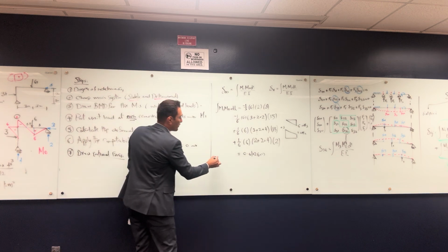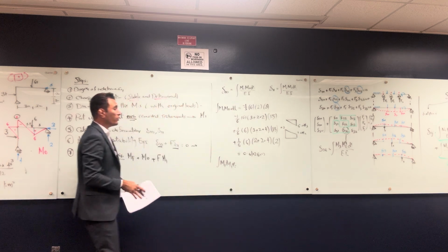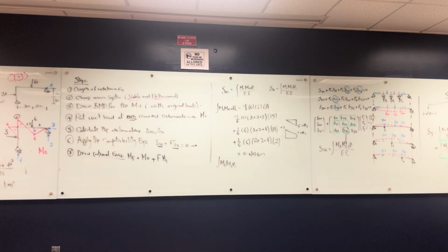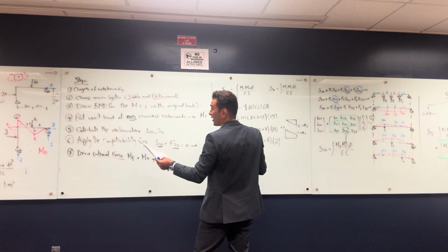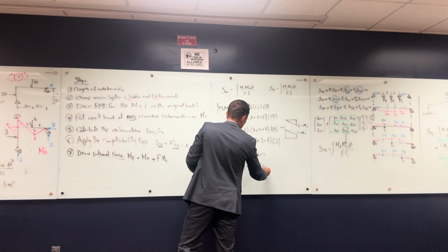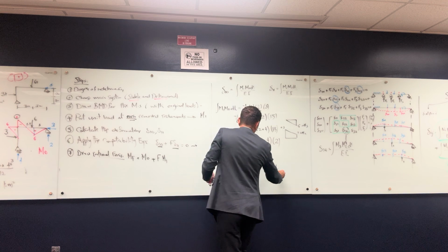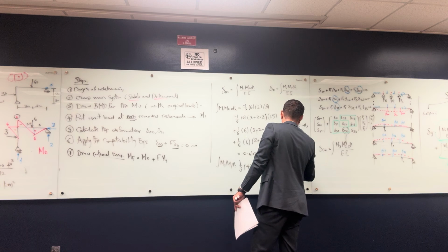All right, same thing, you are going to integrate M1 with M1 DL. How can I do that? That's very, very easy. M1 or delta 1 is the easiest part because it's just two triangles. You are going to integrate them with each other. So if you look at the table, two triangles is going to be 1 over 3, and it's always positive. 1 over 3, M1, M3, so it's going to be 4 multiplied by 4 multiplied by the length 6 plus 1 over 3. And then you have 4 multiplied by 4 multiplied by the length 4.